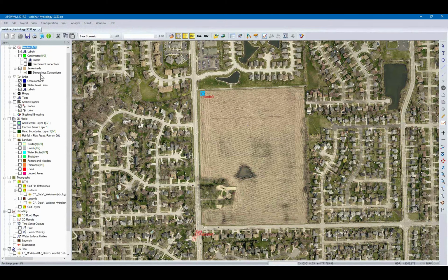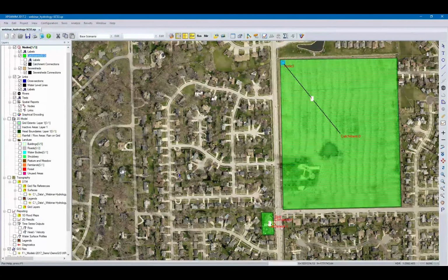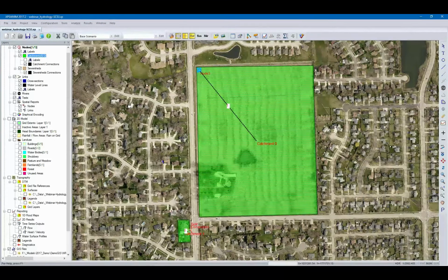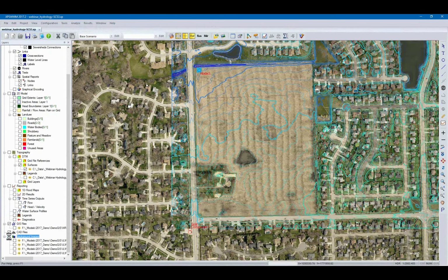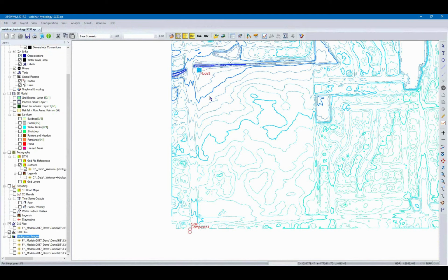So in this case, I have a catchment that is pretty close to just being their property. It's not what I would say is a true catchment where we follow the contours of the ground, although we do have the contours. We're looking for the pre-development release rate here for this webinar. If I turn off the catchment, we can get a little better view. Ultimately, we are discharging underneath a culvert, underneath a road that is off to the west of this project.